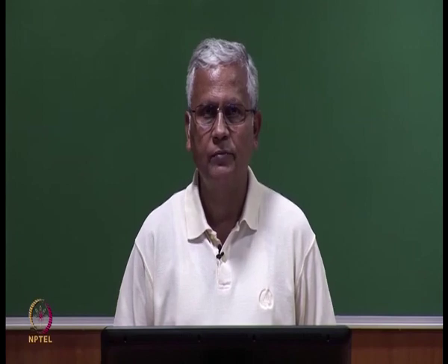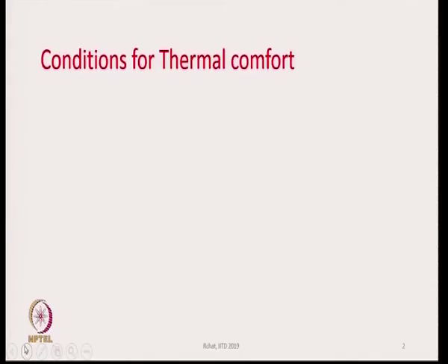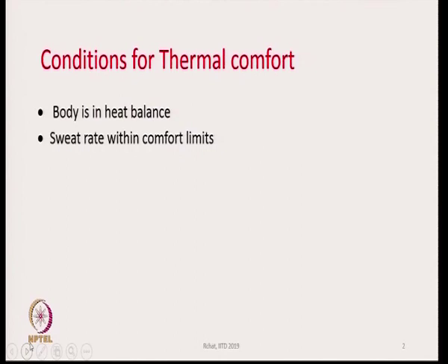We are going to discuss thermal comfort. What are the conditions for thermal comfort? First, the body has to be in heat balance. This is one of the very important requirements. Next, the sweat rate should be within comfort limits. Mean skin temperature should also be within comfort limits.